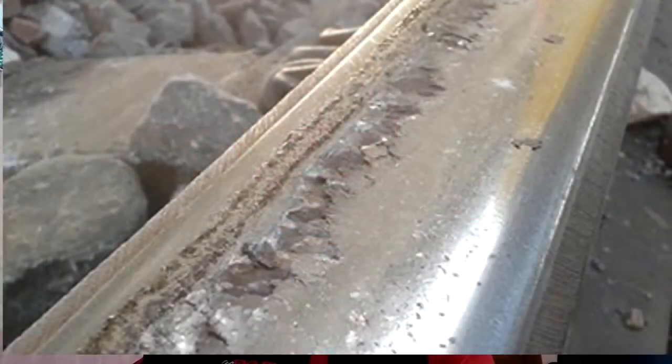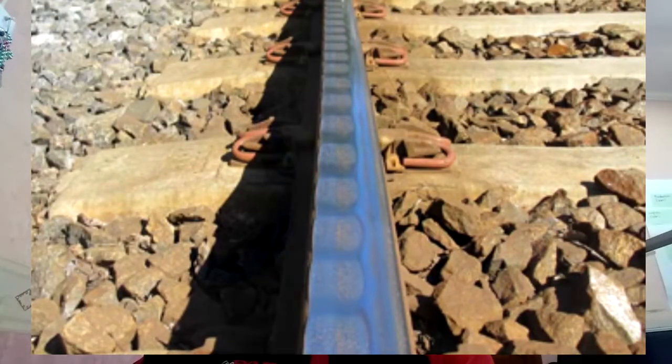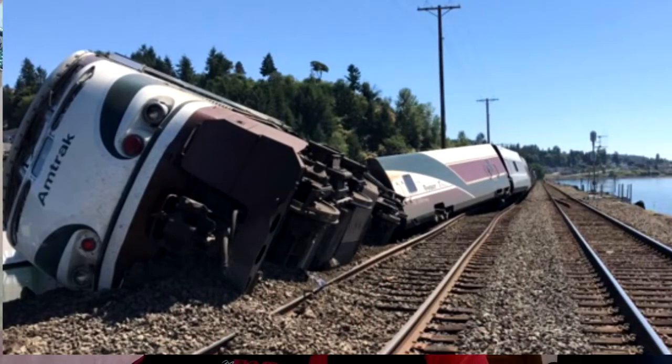Poor adhesion is a serious matter because it will cause high frequency screeching noises, severe rolling contact fatigue, exacerbated rail corrugation, poor braking, and also poor take-off of the train. And if the friction is too high at corners, on curved tracks, it is also able to cause wheel climb and derailment of the train from the rail.